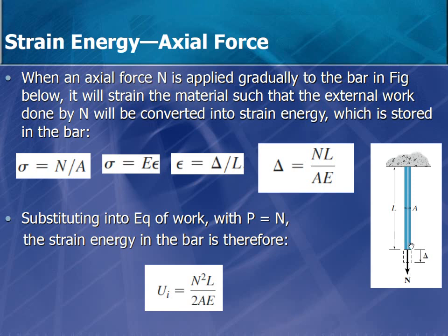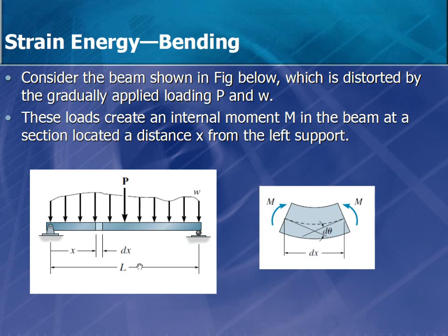So in the case that we have a force here, this force is creating internal force. Any way that you're looking through here, it's the same. But when we have moment, moment depends on the location. So any point that you're taking here, for example, this segment dx, the moment we have has a d theta. So the rotation is different. Take another point, it's going to be different.